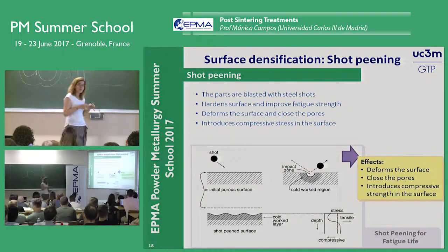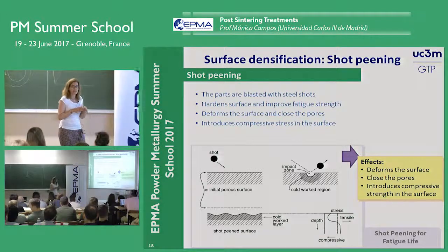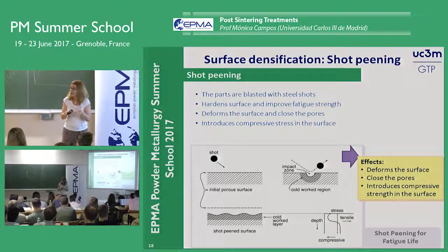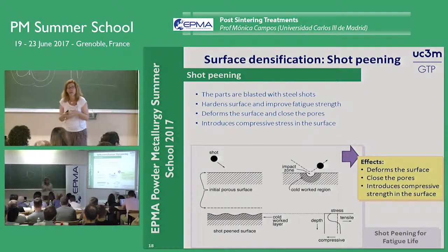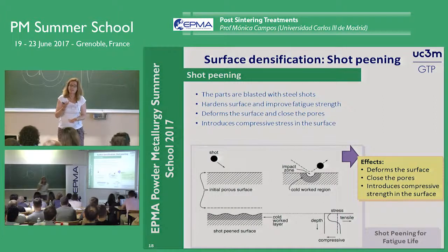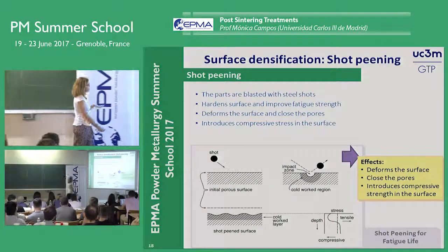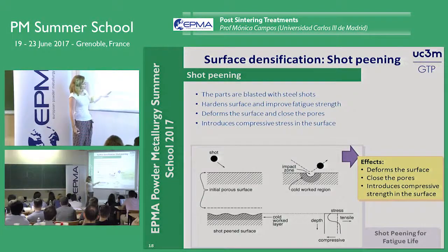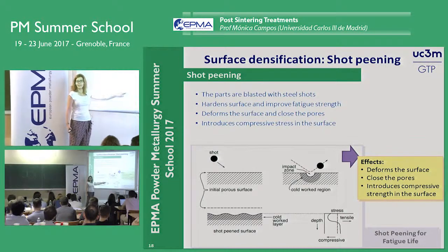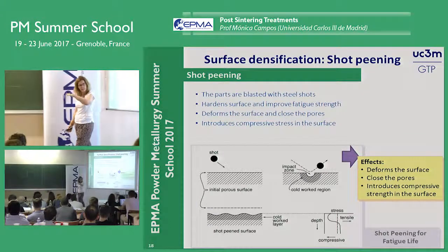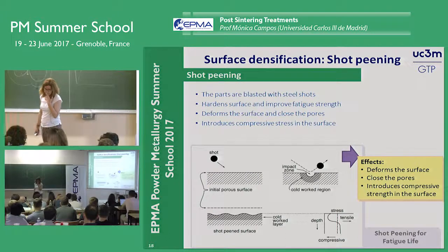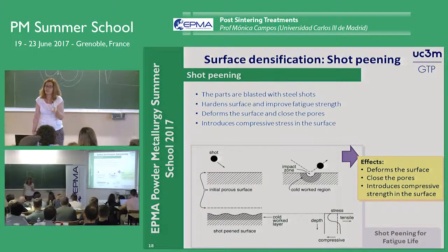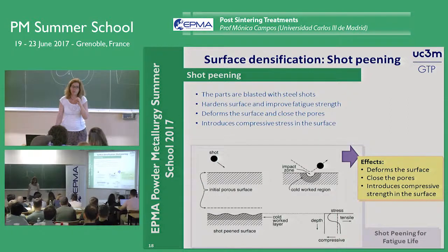We are going to leave there some compressive stress that can help us with impact resistance and fatigue resistance of our component, and we can therefore increase the performance. The point here is that the shot-peened surface is very wavy, and this can be controlled by the dimension, the size of the shot.